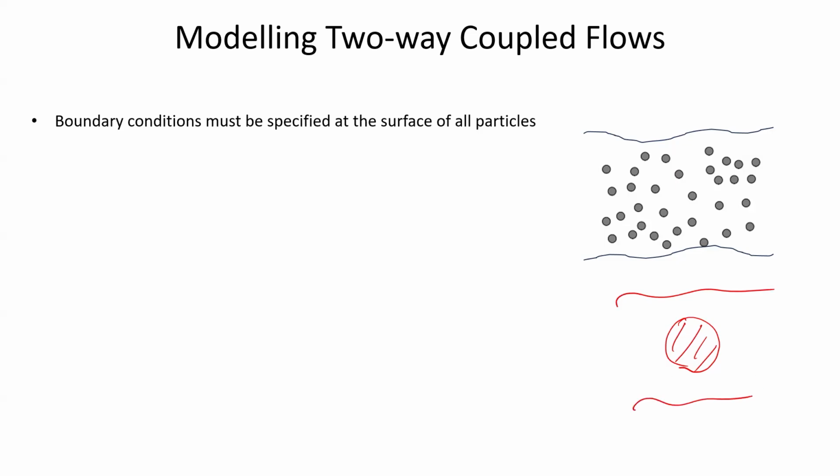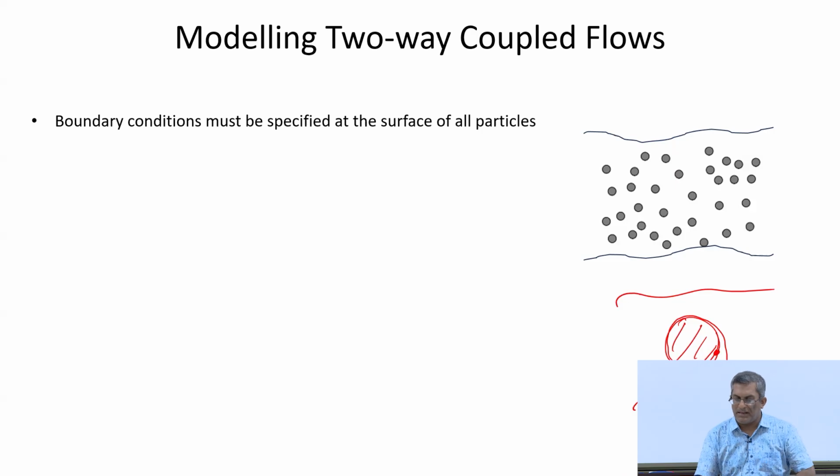So, now how do you solve the equation for the fluid flow? You introduce this boundary condition, that no slip boundary condition prevails here. And that is what you introduce and solve the equations. How you solve it, that's a different thing, but that is how you solve it. Now you imagine there are many particles, and for a moment you assume that the particles are stationary and the fluid is moving. So, this means that instead of one cylinder, you have many cylinders in place.